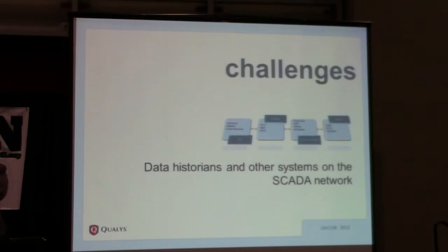Now in a SCADA system, there are a lot of other things on that network. There are data historians, there are web servers. The data historians are typically databases, which could be Oracle, MySQL, and they are affected by the same thing as an operating system is. Oracle releases patches, MySQL releases patches. Do you apply these patches? Does your SCADA vendor really tell you if it's safe or not to apply this patch?